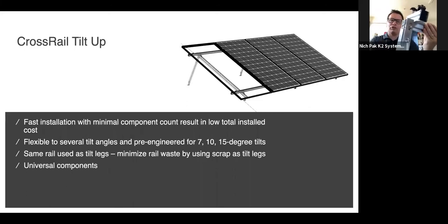So we all know that job site conditions aren't always perfect. So you're going to run into situations where you're going to need the adjustability. We went ahead and thought of that situation when it does occur. So we made sure that this is a slotted hole, and the holes here on the bottom of the tilt assembly kit are round holes to receive those T-bolts.